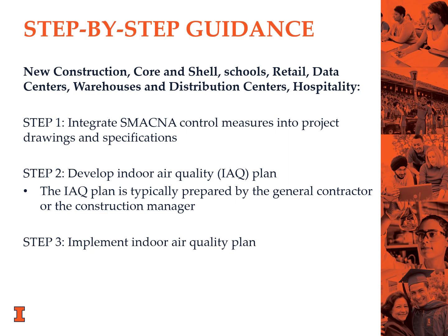Step 3 is to implement the IAQ plan. This plan must be in place prior to starting above-ground construction, storing materials on site, or roughing in mechanical systems. Photographs should be taken of each IAQ measure for the documentation process.